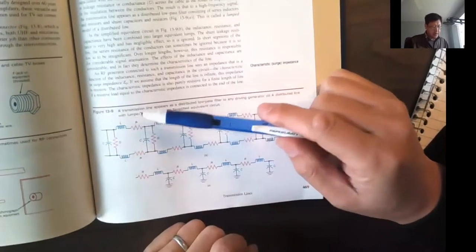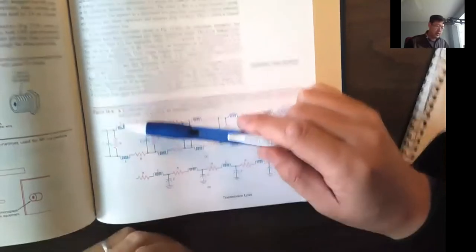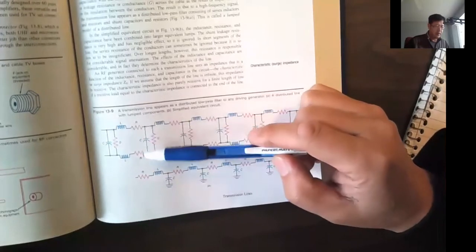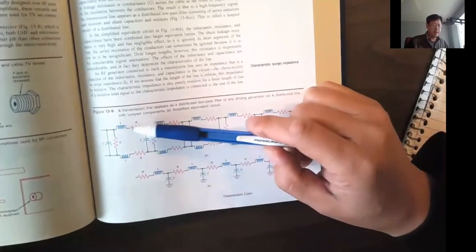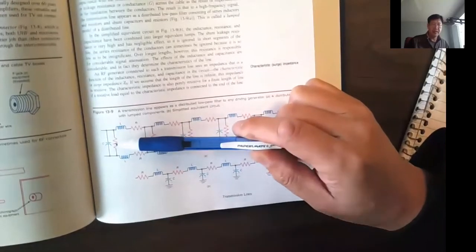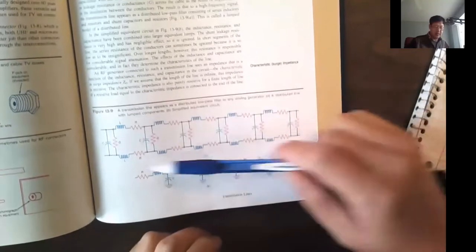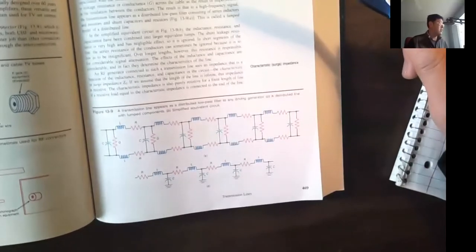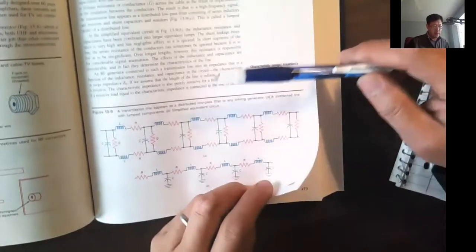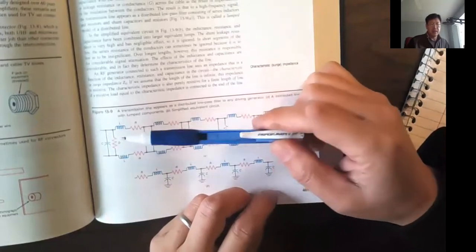This transmission line has resistance, has capacitance, has inductance. In the low frequency range, the inductance and capacitance are insignificant, and so is the resistance even. So we just think about those as conductors. At higher frequencies, the inductance and capacitance become more and more significant. Not the resistance, because the distance is generally not very long. We don't use a transmission line generally to transfer long distance energy. So resistance is insignificant. The inductance and the capacitance become more significant.